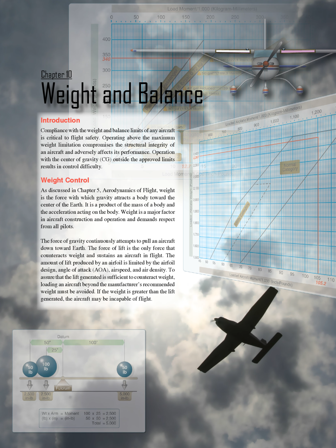Chapter 10: Weight and Balance. Introduction. Compliance with the weight and balance limits of any aircraft is critical to flight safety. Operating above the maximum weight limitation compromises the structural integrity of an aircraft and adversely affects its performance. Operation with the center of gravity (CG) outside the approved limits results in control difficulty. Weight control is discussed in Chapter 5, Aerodynamics of Flight.